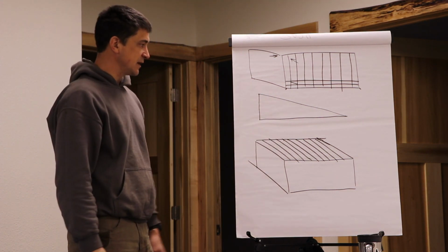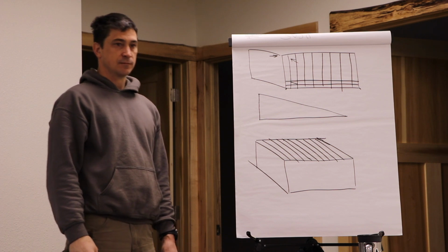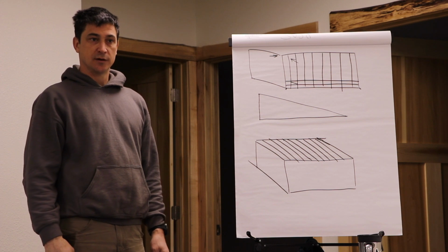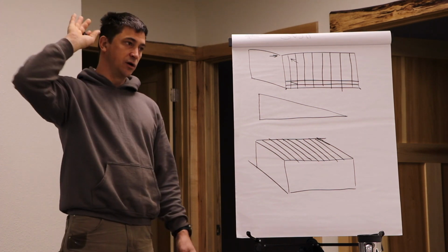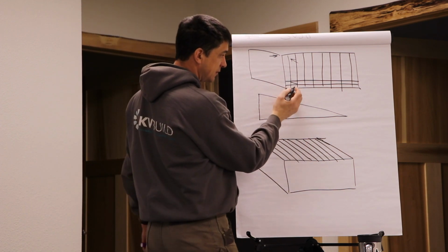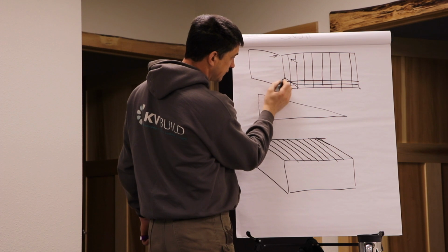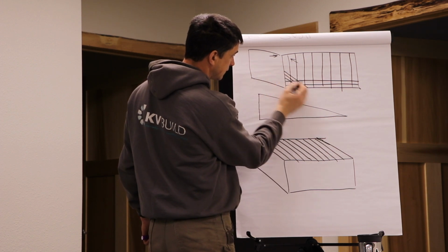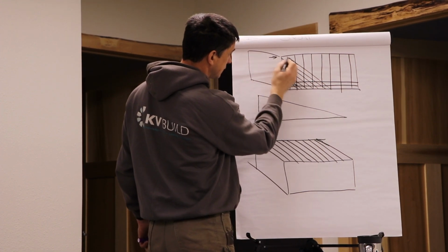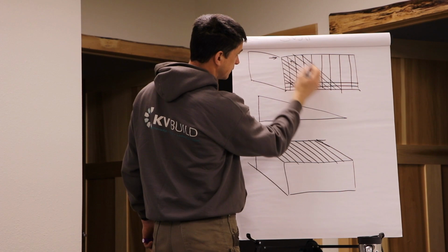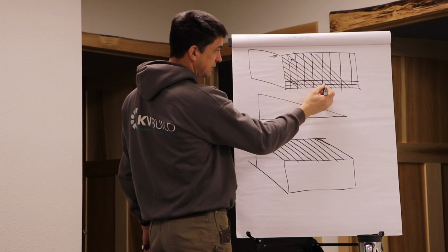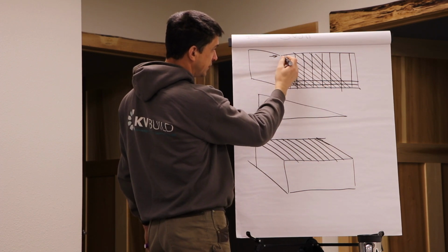Like that's actual size of my bracing. Yeah, we get 500 of those, but compared to the leverage of that tall wall and the wind blowing on it, it's not that much bracing. Where if I run my sheathing diagonally, like that, you get from here all the way to here.